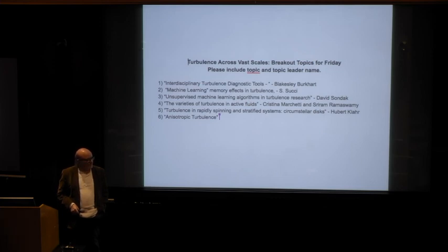Likely, there is another element to this. There is a difference if the flow is forced or unforced. In forced flow, the jets tend to stay separate from each other, and this follows from turbulence properties. If it's unforced, then you will get merging of the jets. It also depends on other parameters, but the flow regimes are very different, forced and unforced.